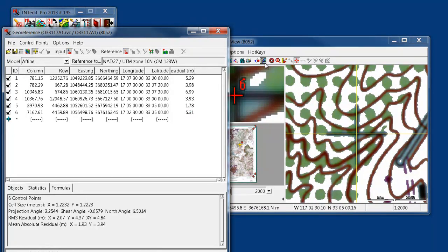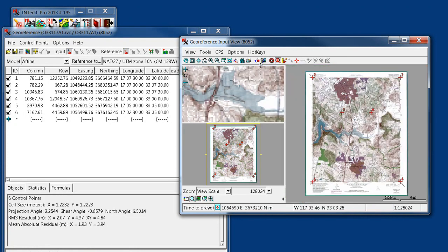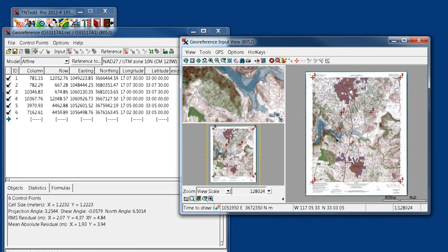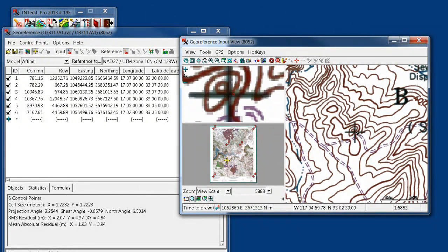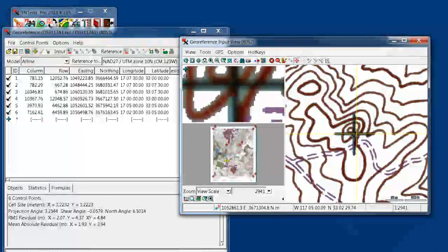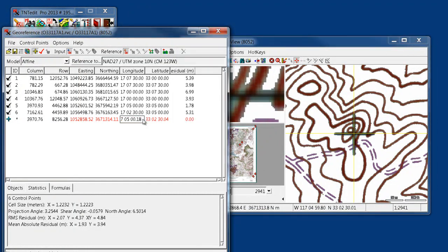Okay, 2 more to go. We're going to zoom, first full scale, and then approximate the location of the point, which is here. Zoom again, set the location of the point, predicts, we're going to get rid of our sub-seconds. Looks good. Check.